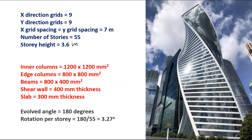1200 millimeters squared, and the edge columns, I'll show you what these edge columns and inner columns are, and the beams 800 by 400, and the shear wall is 400 millimeter thickness, slab is 300 millimeter thickness. So the twist angle, as I mentioned before, is 180 degrees. So you have 55 stories. So the rotation per story is about 3.27 degrees, right?